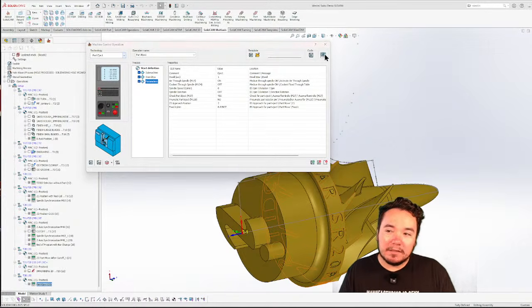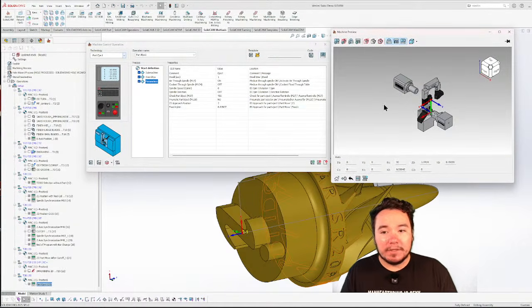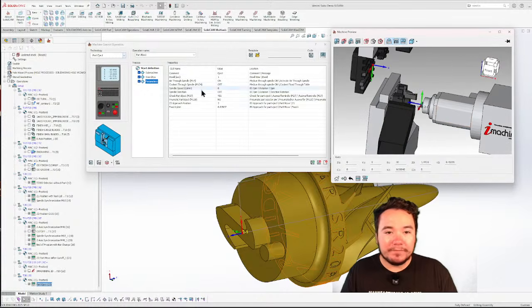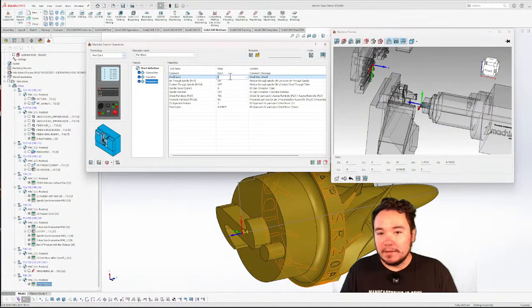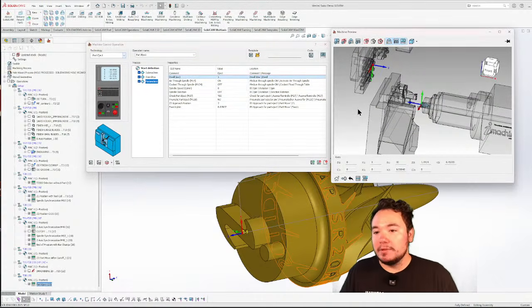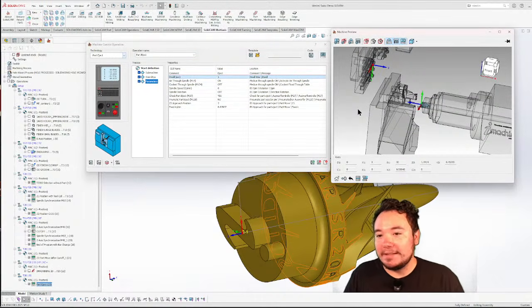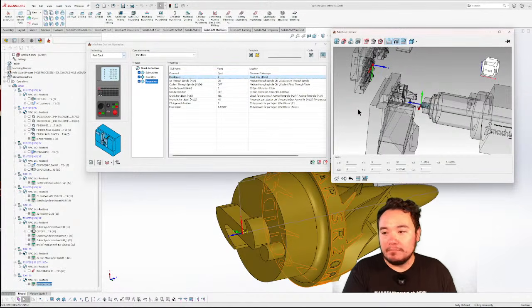And when I did add the part eject, one thing that you do have to add is you can add a dwell in there. It's in seconds. You can do longer, however you'd like to put it. Air through spindle, I turned it on, yes, as well. For this specific one, there's a spring-loaded plunger, so the second that there's no pressure up against it, it'll just shoot it right out.